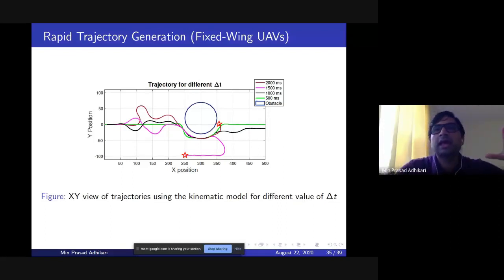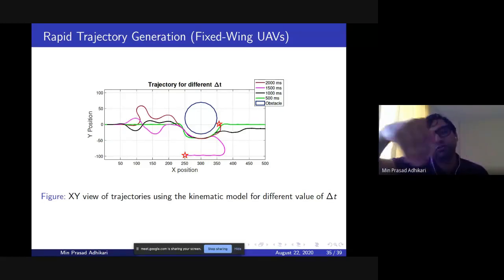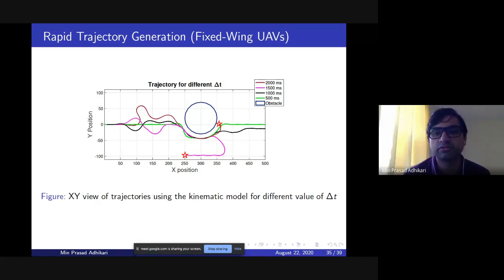One more thing, when we talk about other approaches and just getting a feasible solution: if you are just thinking about a feasible solution, avoiding obstacles, in a quadcopter especially, if there's an obstacle you can stop mid-air and turn left, then choose a straight line to the goal point, or even go back to the trajectory. For the fixed wing UAV, you can still do obstacle avoidance without solving this optimal control problem, but you do not get the best path all the time.